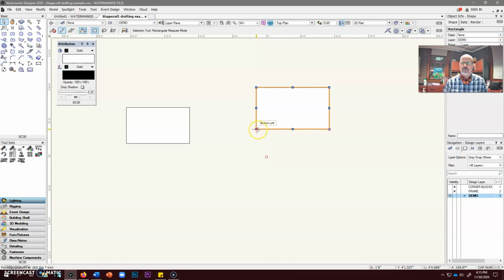These handles have two different ways of operating depending upon what happens to your cursor, your smart cursor, as you hover over those handles. You'll see that there's a plus sign, in which case I can click and drag that element to some other place, maybe snap it to another object or snap it to the grid.